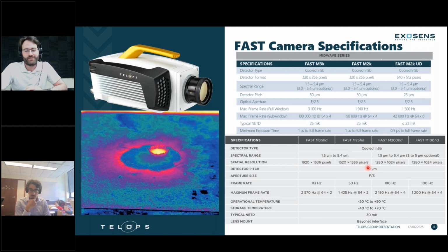But in this field, the midwave series, when we talk about midwave camera from 3 to 5 microns or the extended range from 1.5 to 5.4, it's a good, reliable range, have a good image for the thermal aspect of your scene. And it's also the range of cameras that have very solid detectors with reliable high speed compared to the other bands. So if you do have high speed phenomena happening within your fluid or on the surface of your fluid, that's where you need those models that push the frame rate for your acquisition. So M3K is the fastest model.